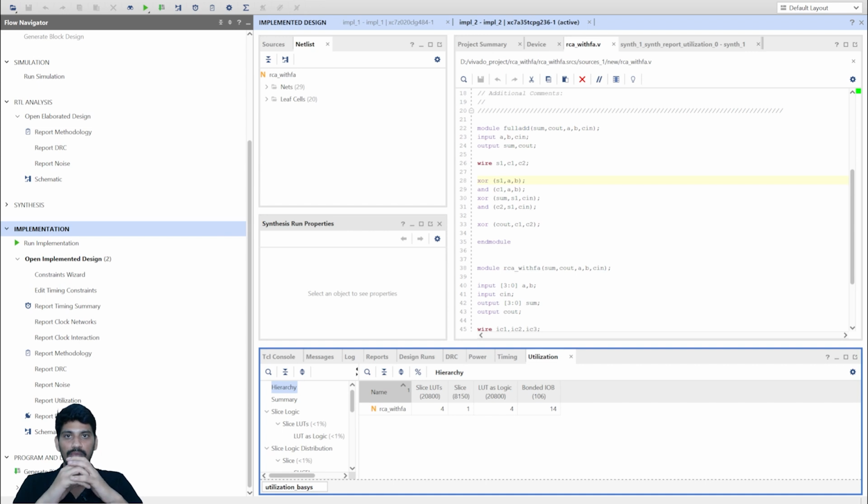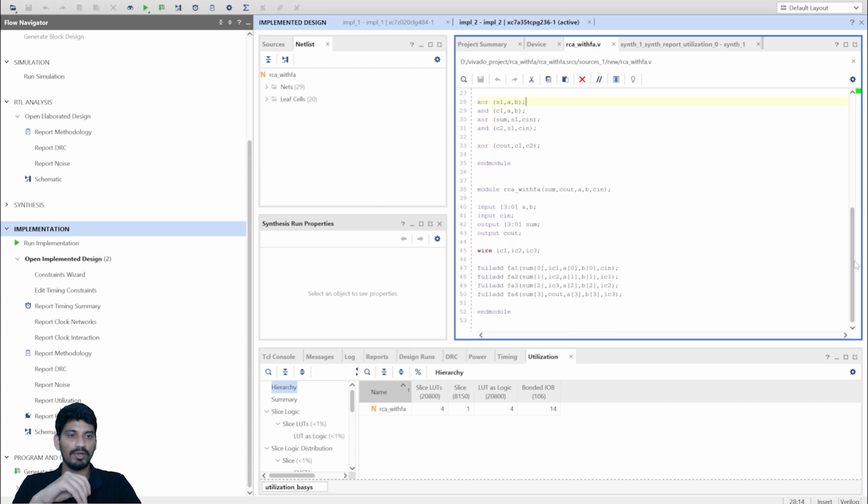Okay, one more example I want to show, the example of gate delay, right? So we'll do that as well. That will clear up the delays I'm explaining. In the ideal world, the delays will be different compared to the simulation world. So I want to emulate the real world delays by adding gate delays in the Verilog code.